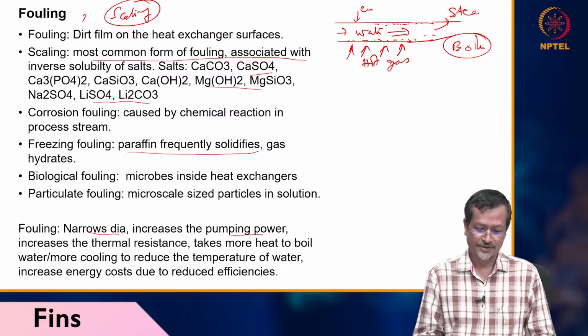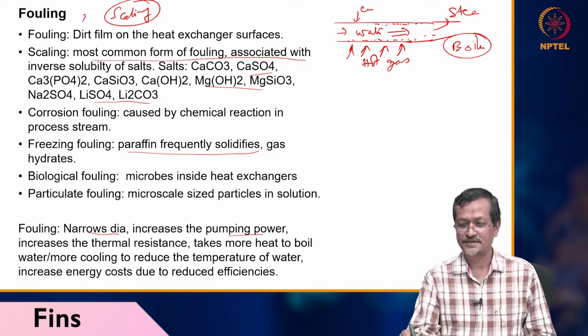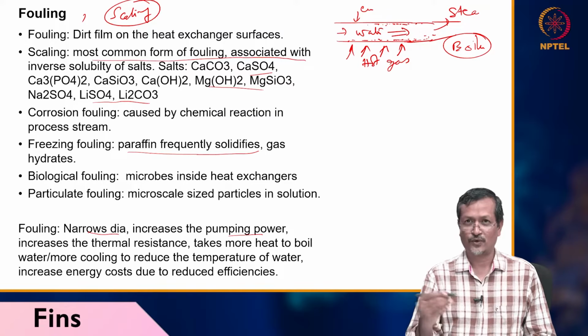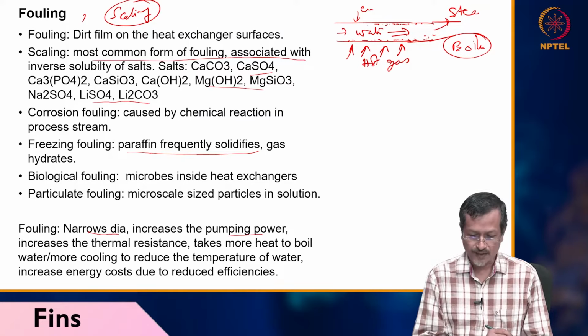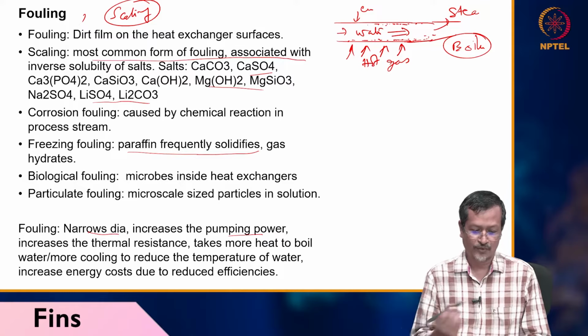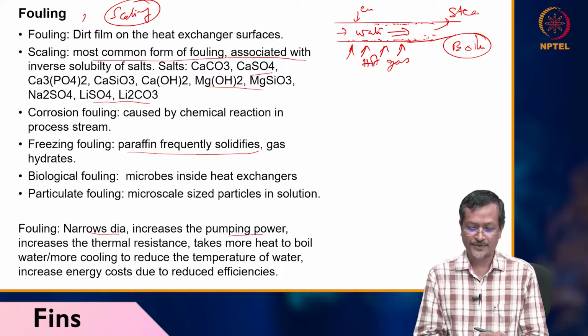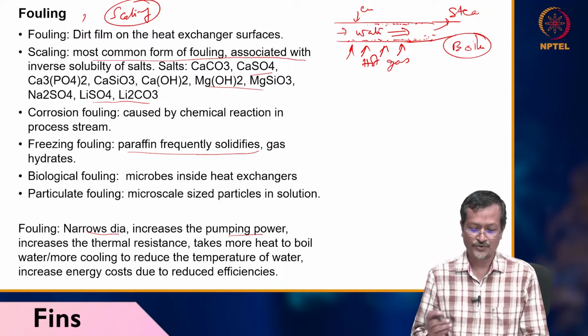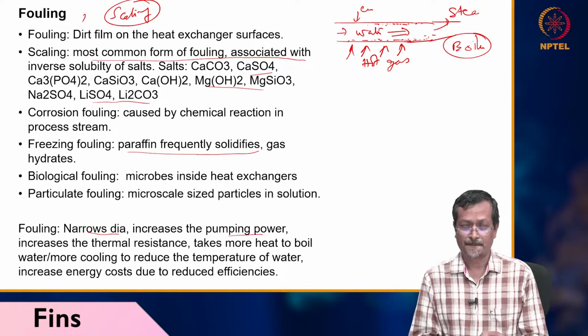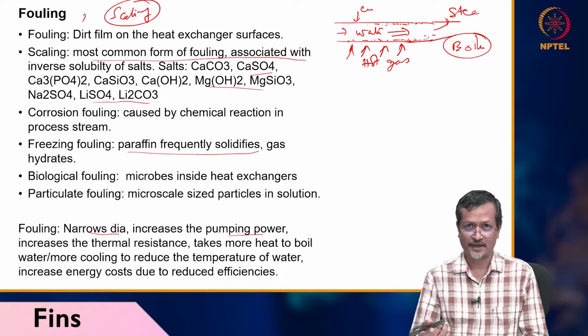It also increases thermal resistance, because this fouling has lower heat conductivity, so it takes more heat to boil water or more cooling to reduce the temperature of water, or increases energy cost due to reduced efficiency. So fouling has a negative effect.